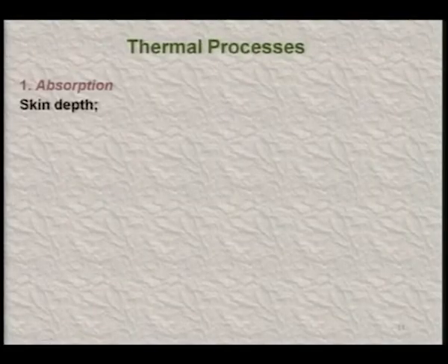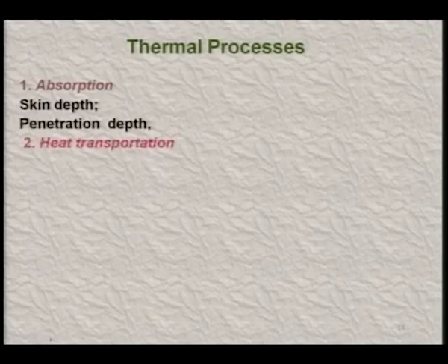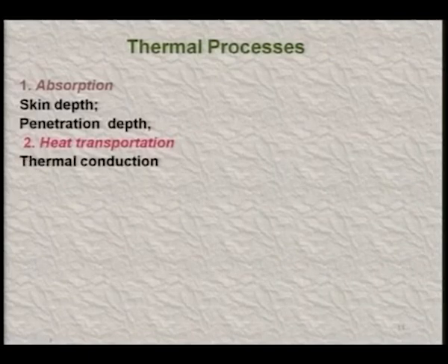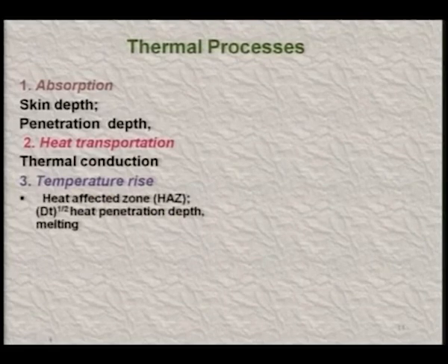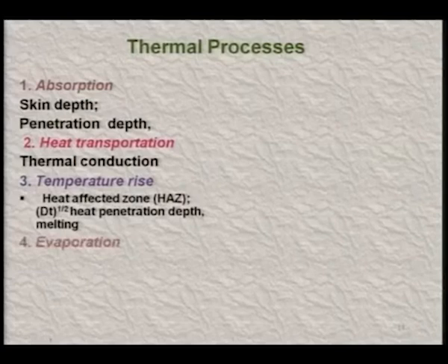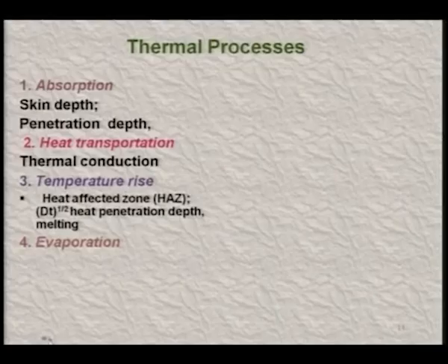Now, there are various thermal processes that take place during laser beam machining, such as absorption, which depends upon skin depth and penetration depth, and heat transportation, which is a function of thermal conduction, then rise in temperature of the workpiece material. It also decides the heat affected zone, heat penetration depth and melting. Then evaporation, again as I have mentioned already, depends upon the thermal properties of the workpiece material, like latent heat of evaporation and melting temperature.